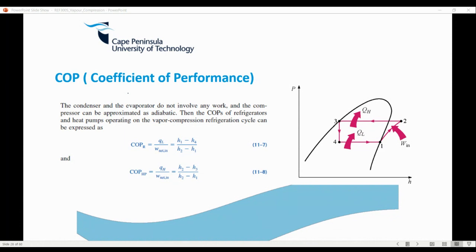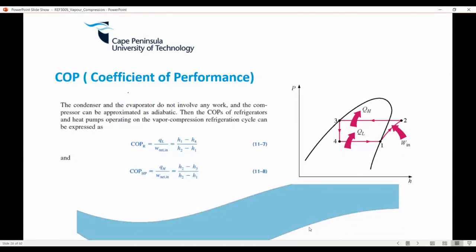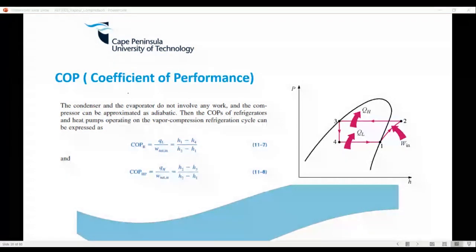And what I mean by this is that if you look at the direct energy conversion, it's really, really efficient. You get a COP of anything from 2 to 4. So what I mean is that if you put in 1 unit of electrical energy, you get around 3 to 4 units of thermal energy. So it's a very, very efficient device.